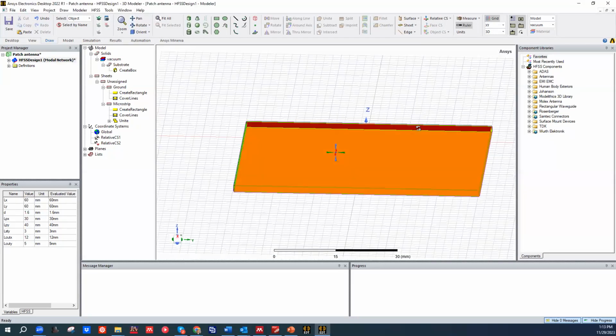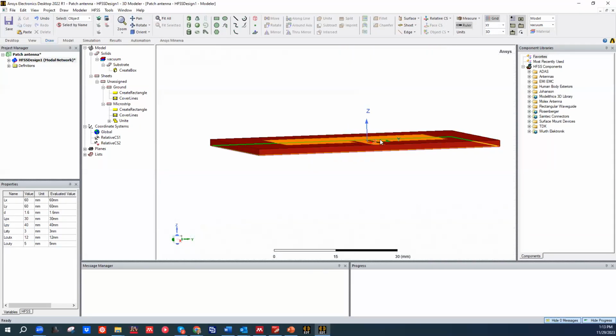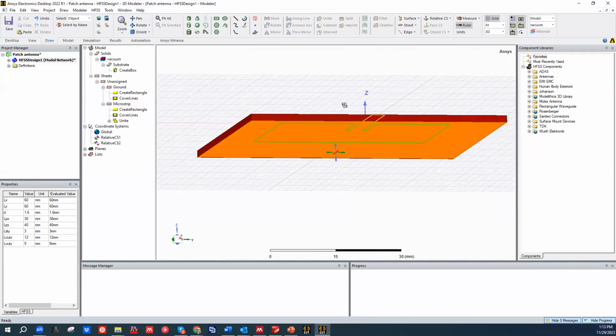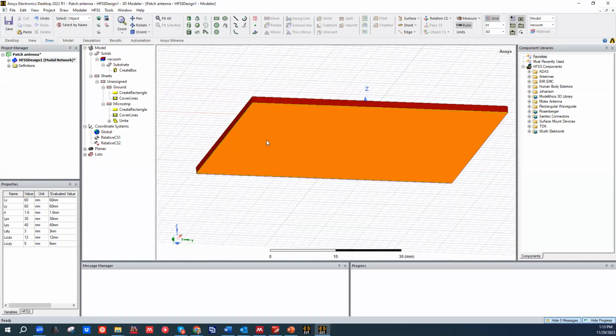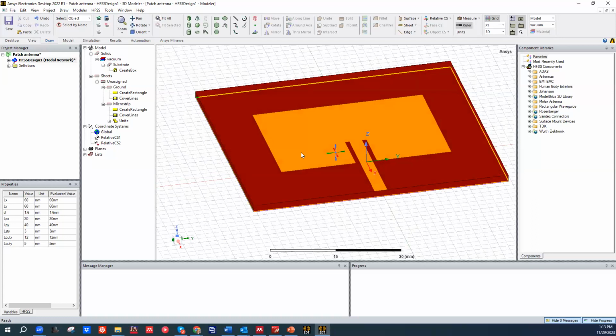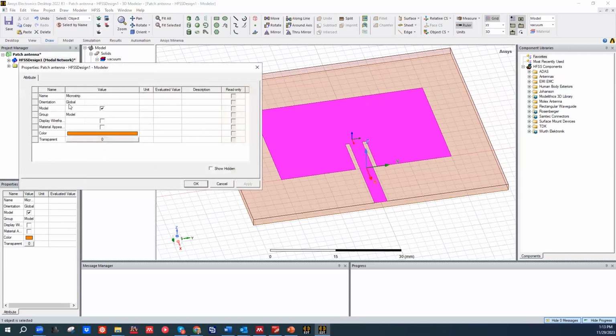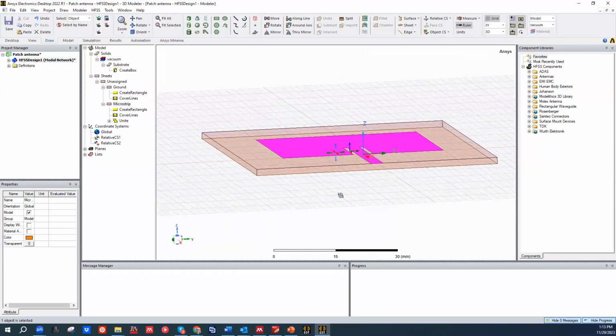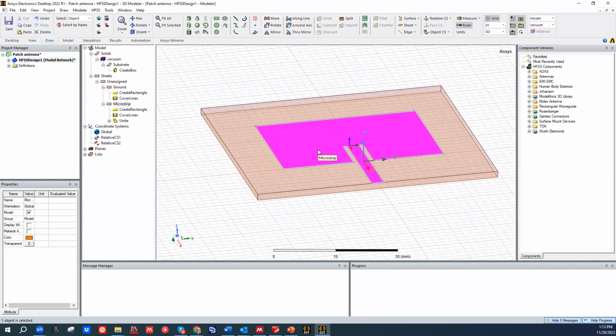All right, so this is the structure of my antenna, but it's made of nothing for now, right? I need to give it a material. In ANSYS HFSS, I cannot assign a material to a rectangle, right? A structure without any thickness, with zero thickness. I cannot give it a material. So I must consider the rectangles as a perfect electric conductor, so basically a perfect metal.